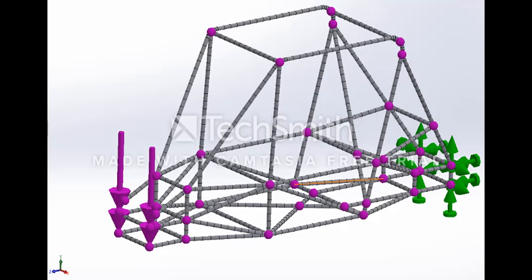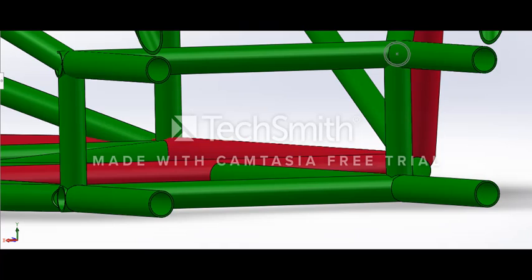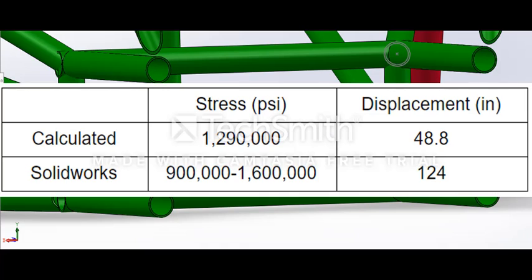the wheel fixture. For our closed form solution, we fixed the rear of the vehicle while loading the front with a downward force of 26,000 pounds. By simulating the vehicle as 4 simply supported cantilever beams, we were able to calculate the bending stress, which closely matched a SOLIDWORKS solution. However, the calculated deformation varied from the SOLIDWORKS value, possibly due to an oversimplification of the